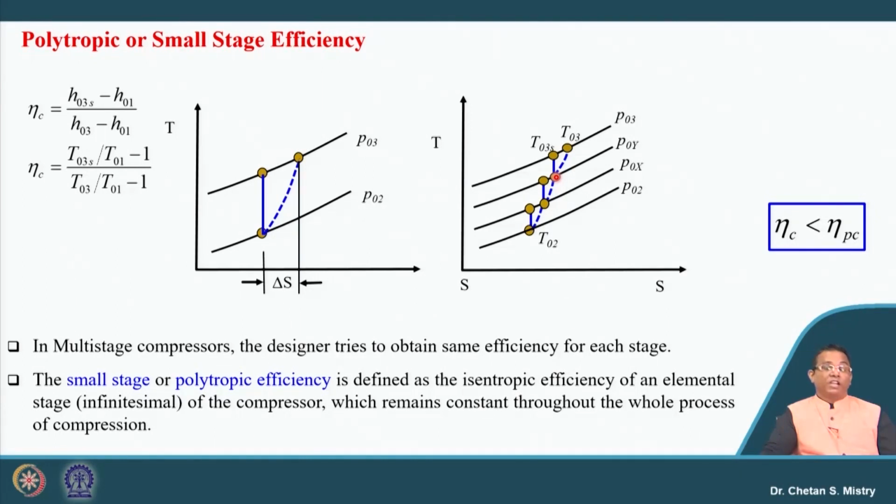So, here we need to observe a very important thing that is happening when we are going with the multi-stage configuration, or we can say per stage configuration. What is our observation? Here, this is representing my isentropic temperature rise for the multi-stage configuration, and here this is representing my isentropic temperature rise when I am considering a single stage or single configuration.